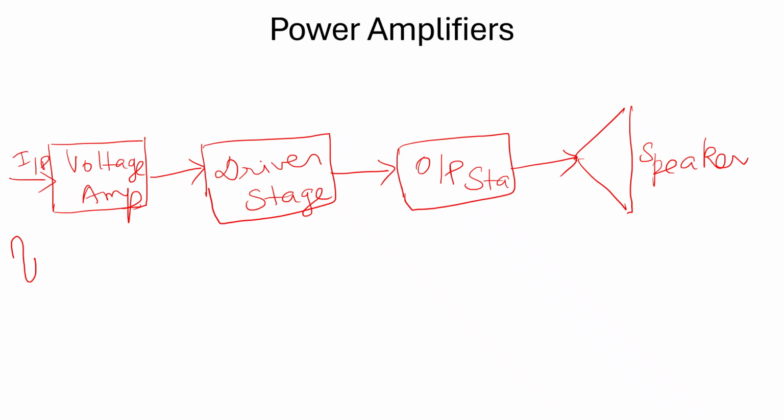What do these amplifiers do? Voltage amplifiers have quite a small difference from power amplifiers. Voltage amplifiers are low level amplifiers and power amplifiers are amplifiers which increase the amplitude of higher levels of voltages. So when this is given to a particular voltage amplifier, the amplifier increases the amplitude of the signal. It depends on the type of amplifier we are using. If it is a common base, we will get this kind of amplitude. If it is a common emitter, the amplitude is increased with a 180-degree phase shift.